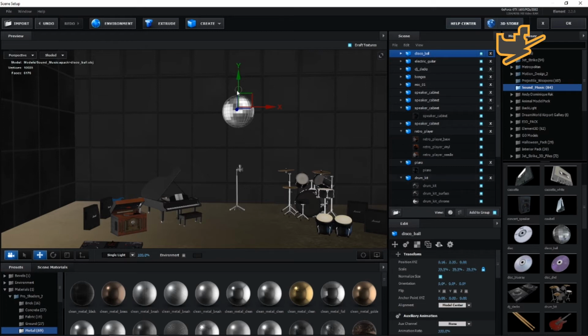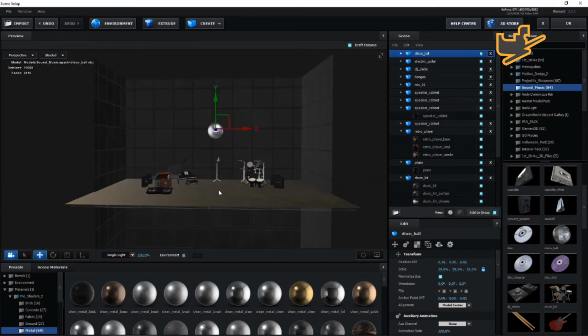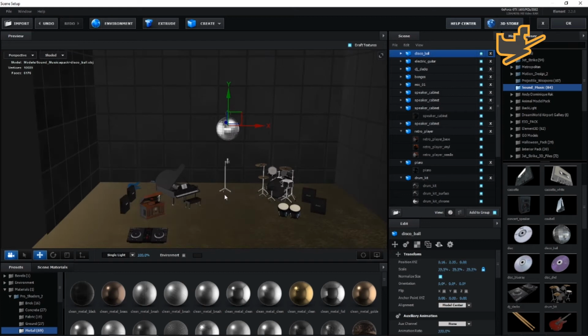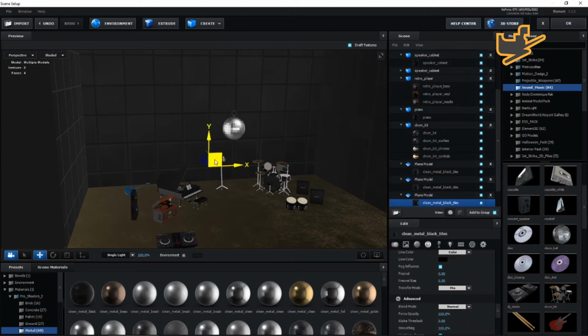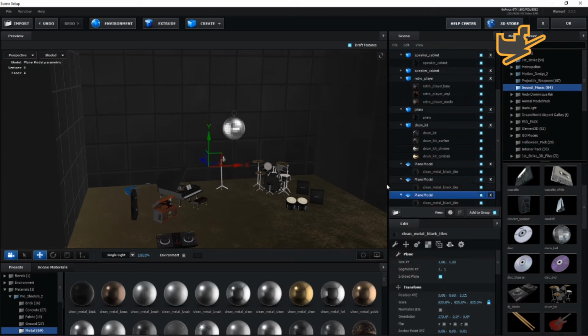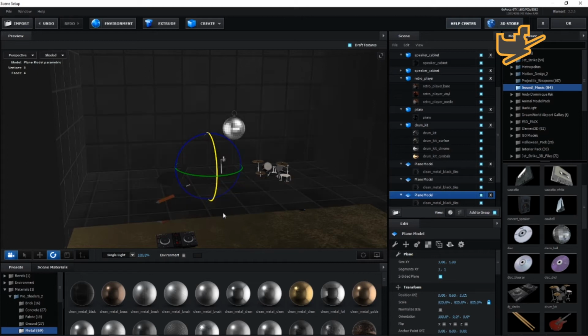You have some chain to adjust it with the ceiling actually. You can make these walls on the ceiling. How you can make the ceiling: just control select it by pressing the model, hit control D to duplicate it, go for move tool, hold shift and make it like this.